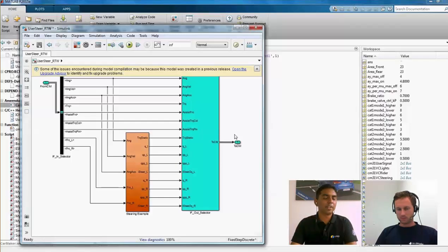People who are not much familiar with the real-time environment of CarMaker, or IPG's real-time environment, we have a product line which is called XPack4. XPack4 has a very similar environment and can run CarMaker on a real-time level, and there again we can use a similar CarMaker.tlc Target Language Compiler and generate an executable for this CarMaker XPack4 platform. So you can generate a real-time executable from MATLAB, and this can run on our real-time environment exactly the same way it is running on a Windows environment.